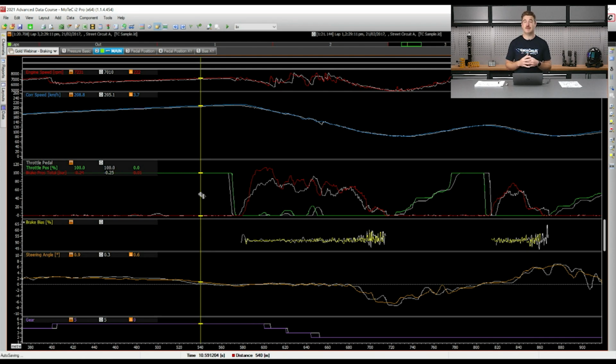It is the most difficult thing to get right in the car, as far as being repeatable, your brake trace being right, your style of braking, all of that. As well as your bravery, and how deep you can go into the corner as needed. All of these factors mean that looking at brake data is probably one of the most common things you'll be doing, particularly when you're working with a less experienced driver.